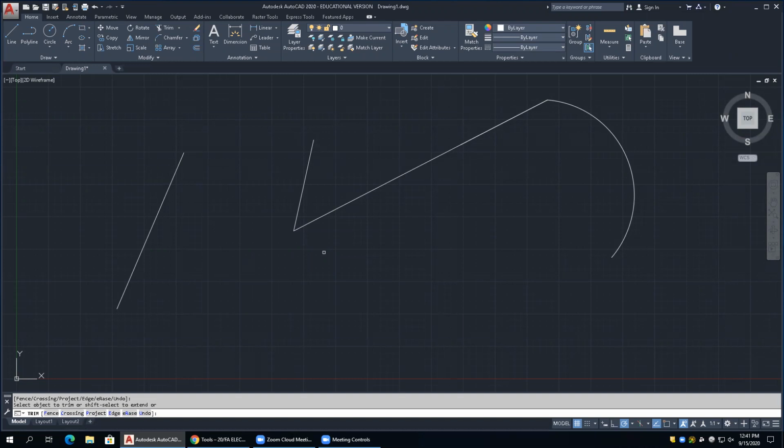Hold the shift key, hold it down. No, you just cancel. Okay. Go back into here. This is the shift key. Hit trim. Hit enter. Okay, so hold the shift key down. Click on this. Hit extend it. You see that? Now release it. Release it, and it'll trim. Okay. You see how that's working? It's going to take a little getting used to. It gets easier. Definitely gets easier.